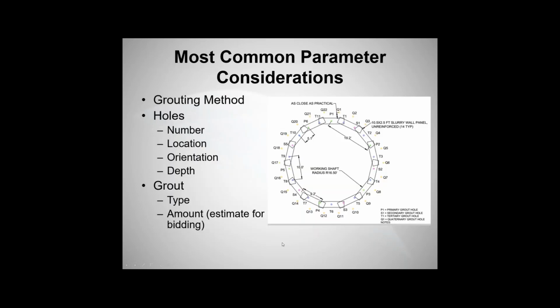That being said, a lot of that information is going to come into focus once we can decide on a grouting method. And 100% the grouting method has to be based off of the geology. So everything that Adam talked about, all the geologic testing, all the information that needs to be gathered, goes into determining your grouting method. Once you determine a grouting method, there are a lot of rules of thumb, conventions, and empirical information that can be used to develop a proper grouting program. So you determine the grouting method, and then after that, there's not that much typically that really has to be figured out to do a good grouting program.